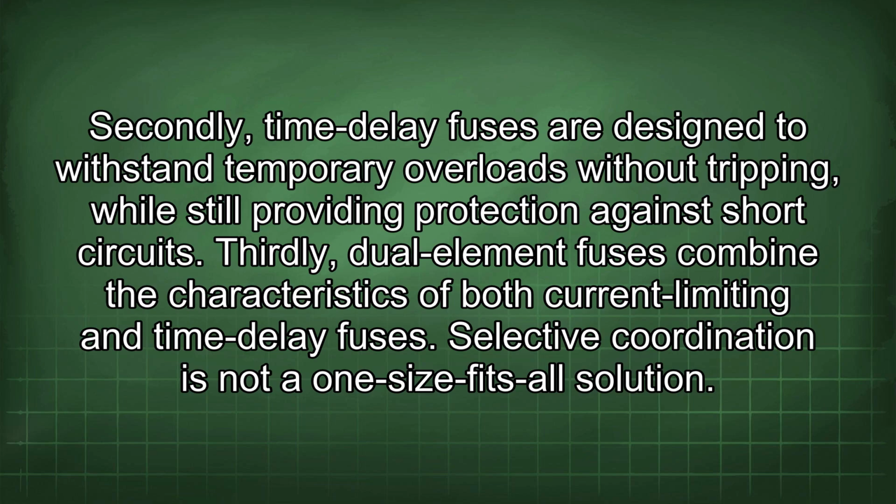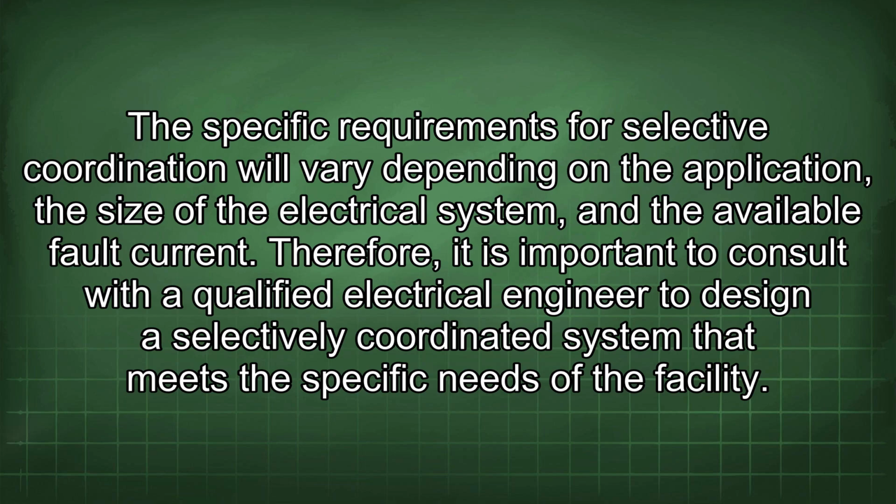Selective coordination is not a one-size-fits-all solution. The specific requirements for selective coordination will vary depending on the application, the size of the electrical system, and the available fault current. Therefore, it is important to consult with a qualified electrical engineer to design a selectively coordinated system that meets the specific needs of the facility.